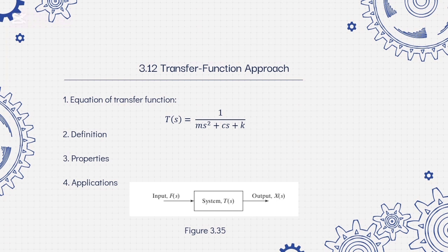It simplifies differential equations into algebra, enabling engineers to predict response to any input and identify resonant frequencies, or reverse engineer unknowns like damping or stiffness through experiments. By applying a known force and measuring vibration, the transfer function bridges theory and practice, underpinning everything from aerospace stability to noise-canceling headphones. Its elegance lies in transforming complex dynamics into a universal tool for control, testing, and innovation.